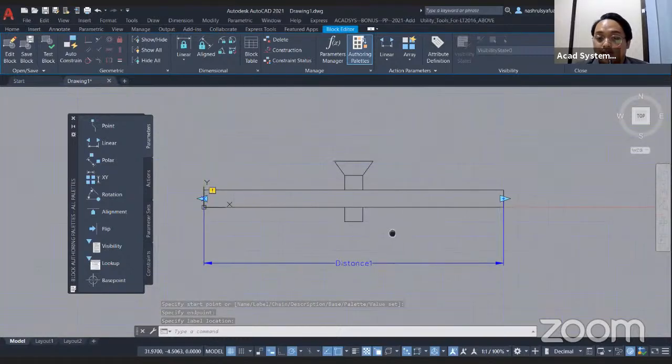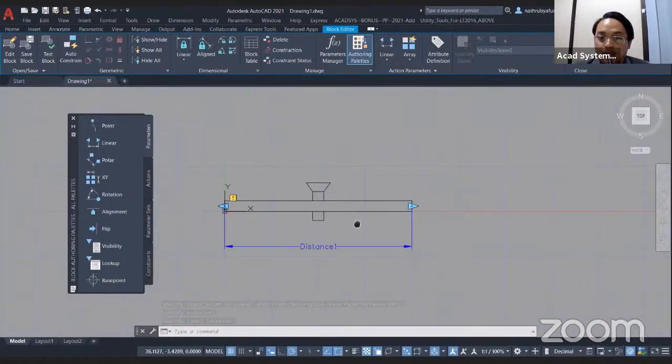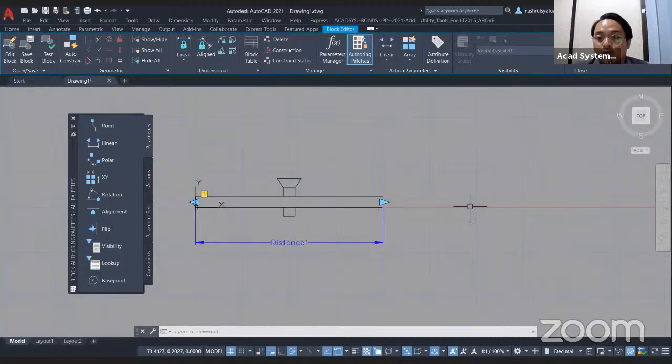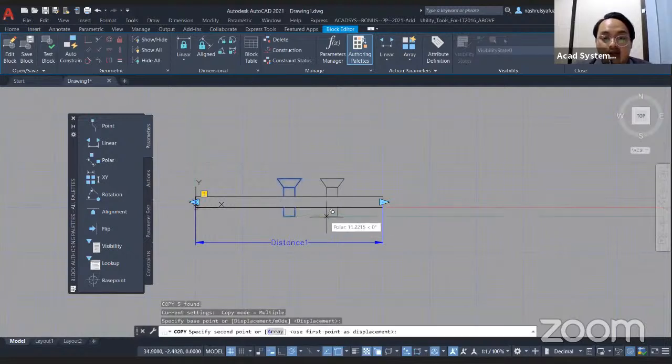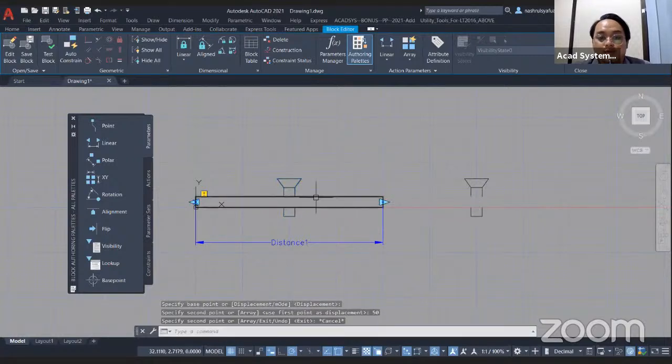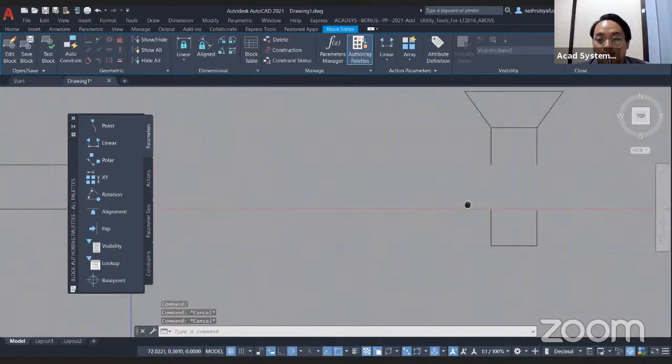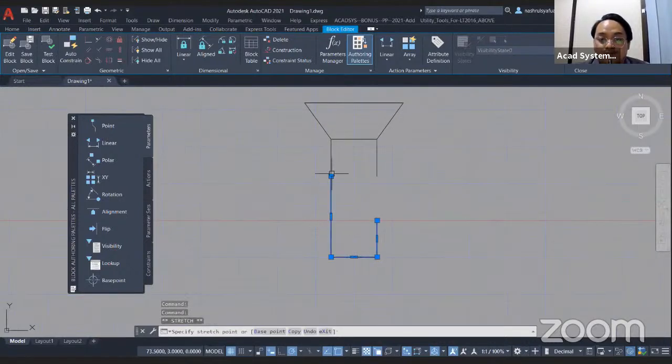Now we have this. So I will create one more block to the right for the wipeout tool. Just copy and then I will move it 50. Why 50? Because my bar here is 50 units. And then just combine it.